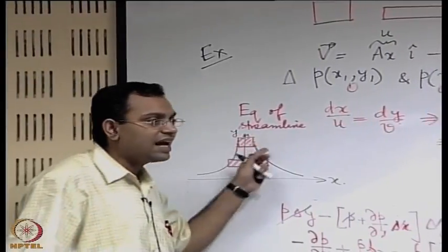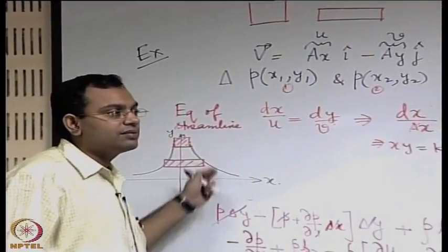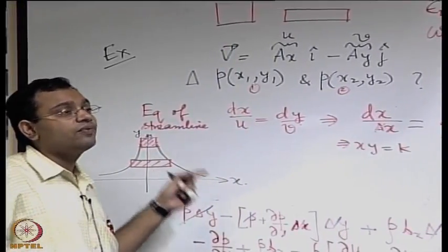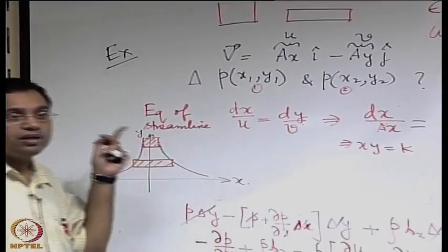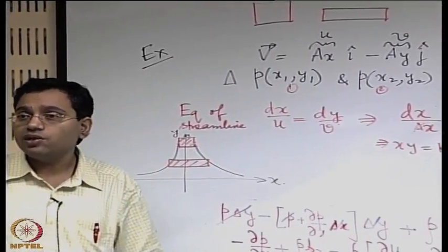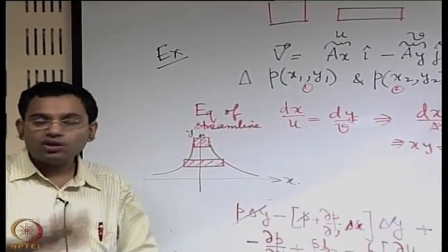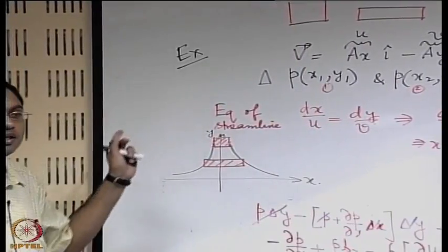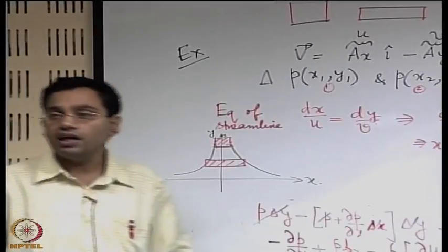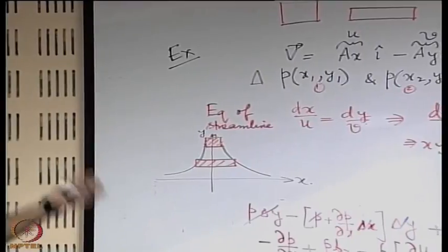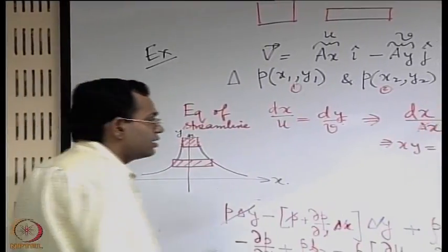So it does not have any effect of viscous shear, it does not have any effect of rotationality. So it is effectively like an inviscid and irrotational flow, and for such a flow we will show later on that you can apply Bernoulli's equation between any 2 points in the flow field disregarding where they are, and we will now go into a more rigorous way of establishing this very important consideration.